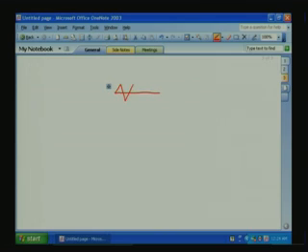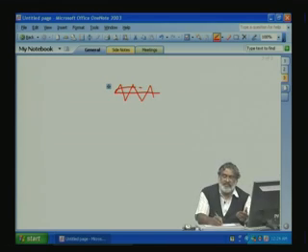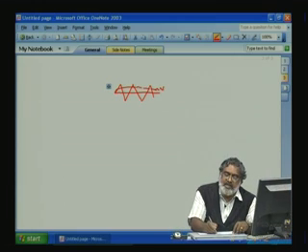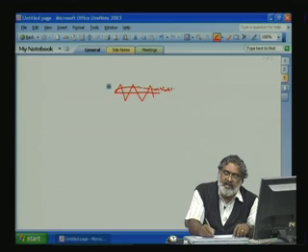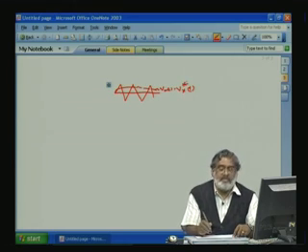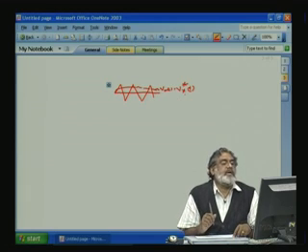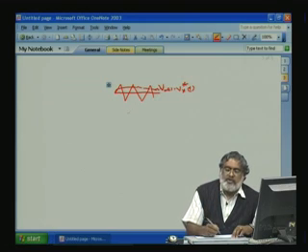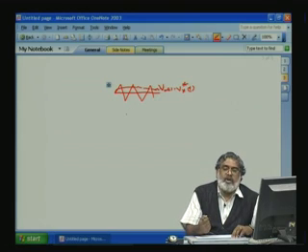This is the triangle signal, and we are comparing it with a sine wave. The comparison is based on this Vm. The triangle wave is fixed, and Vm is our present VRT reference. So, this VRT is coming from our control signal. Okay. So, that will control our converter.